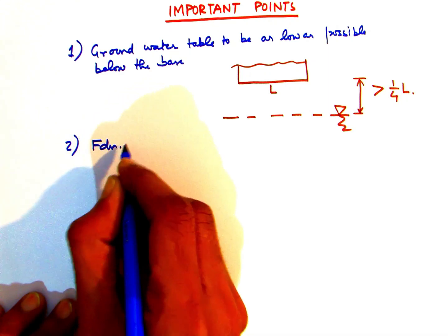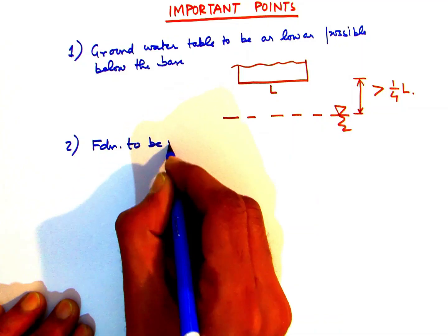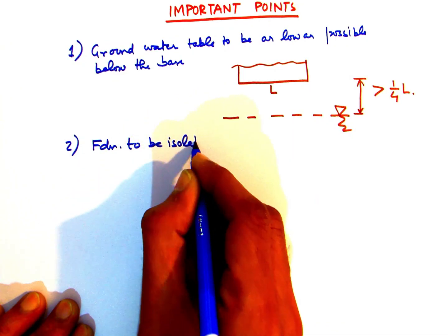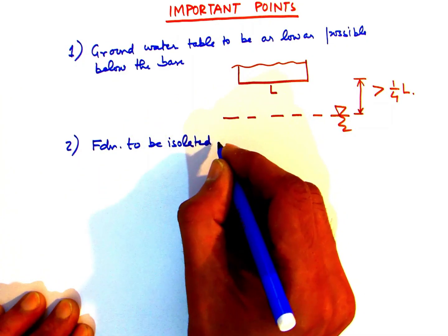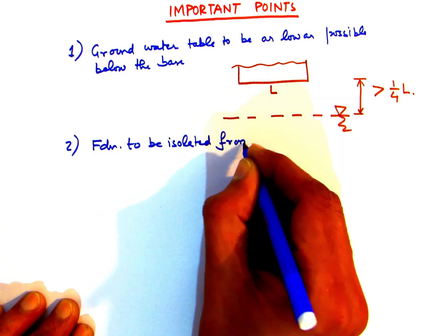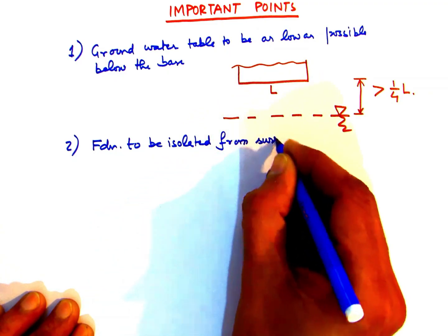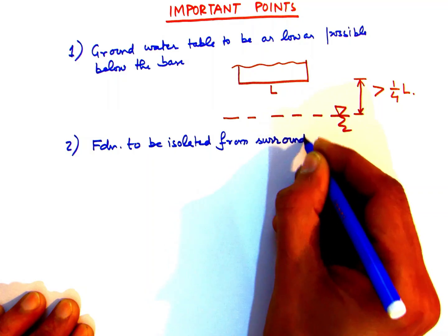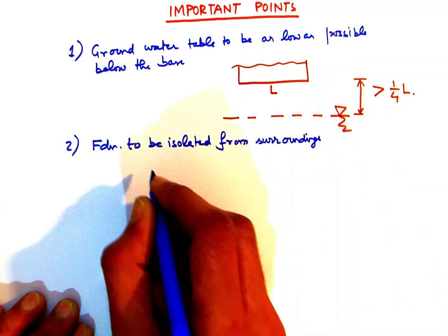the foundation system. However, often we have to do a trade-off because the geotechnical engineering report must be suggesting some minimum depth for the foundation block, and that has to be adhered to.